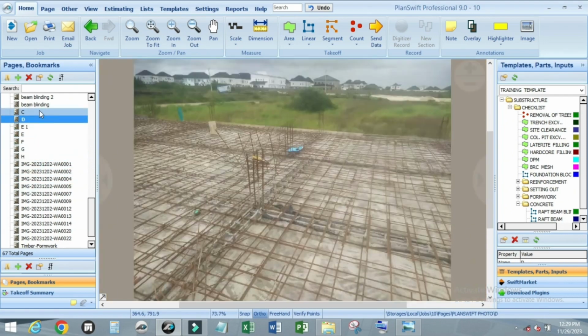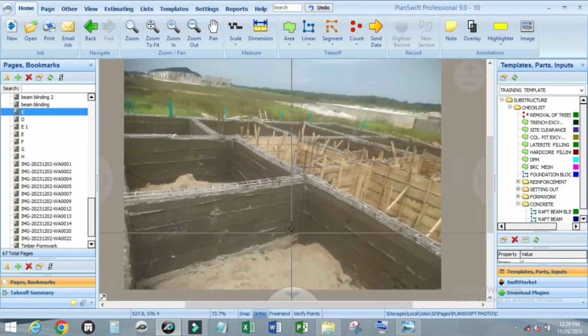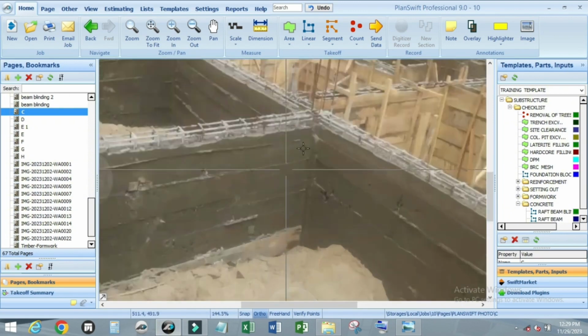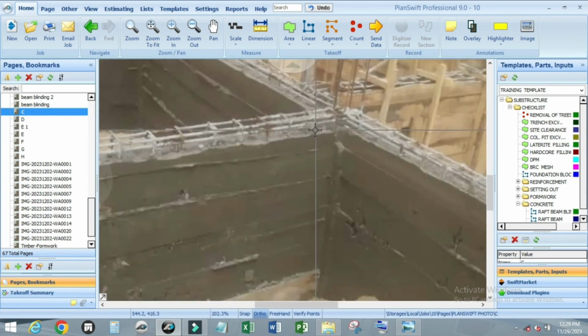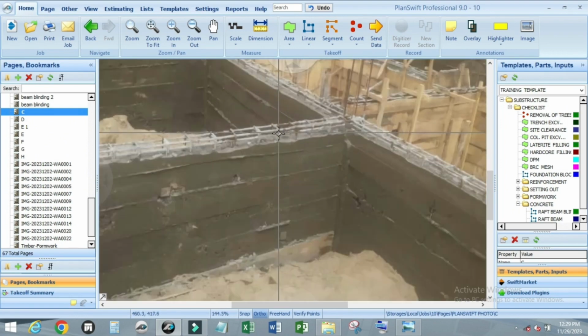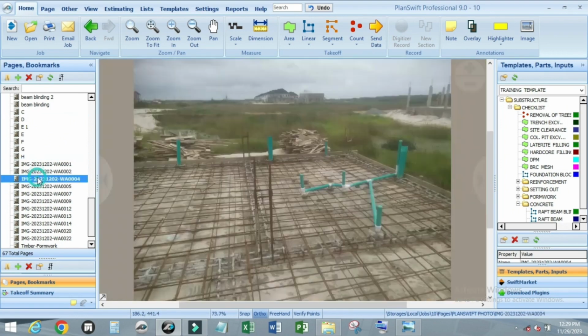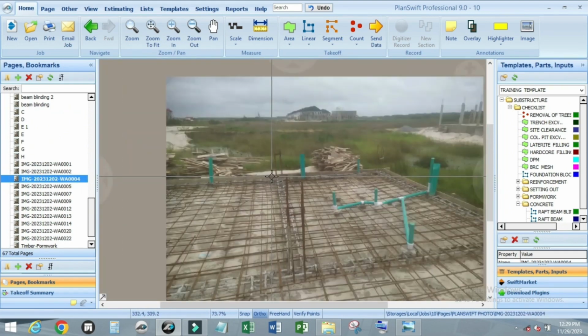So, can you see what I explained the other time? This is the raft beam, which we use 1 meter as the depth, and it remains some space here. This space is meant for the raft slab. So after filling up this space, we lay DPM, we now spread another blinding on it, then we now fix the reinforcement. It is being done here. We now fix the reinforcement. After the reinforcement, we now cast it.